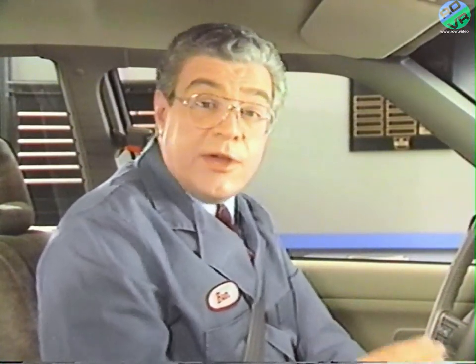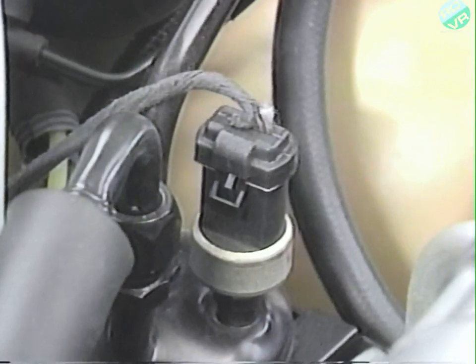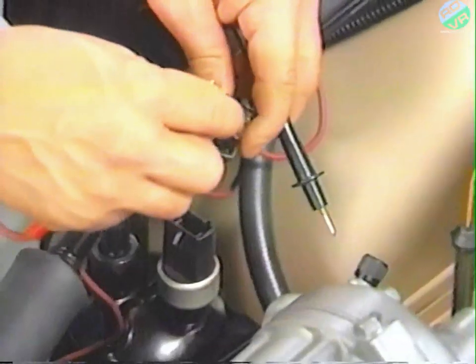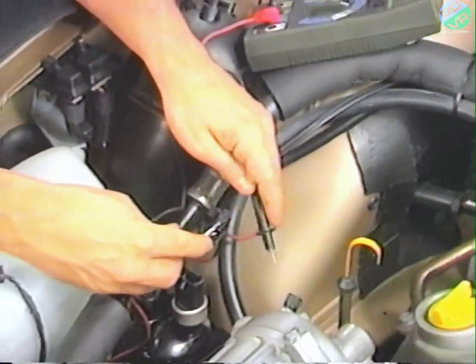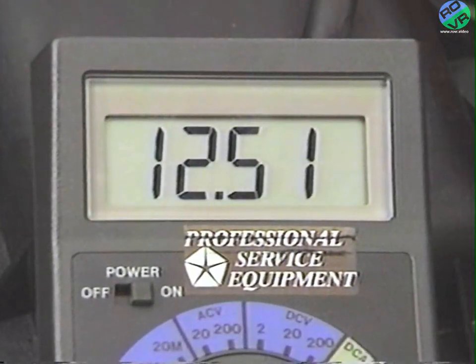For some checks, you can use the readouts from the self-diagnostics to help you narrow down the possibilities. For example, suppose the AC clutch is not engaging. If the AC clutch status readout indicates the clutch cycling pressure switch is open when it should be closed, the problem is in the switch circuit, or low refrigerant. You can narrow down the possibilities by checking for voltage at the switch when the ignition switch is in run. If there is voltage, the switch ground, or low refrigerant is to blame. We'll see a procedure for checking for low refrigerant later in this program.